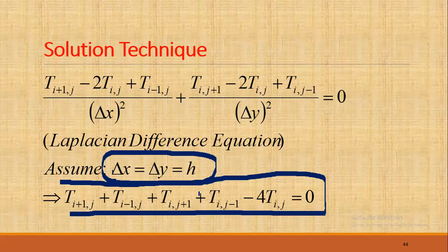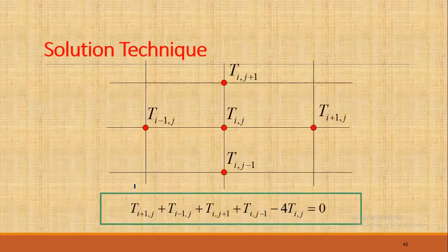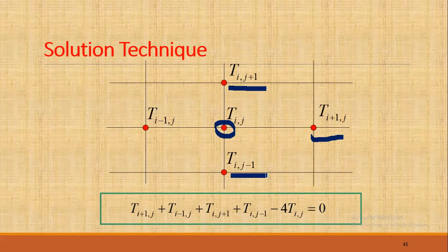And we develop the program in a similar way as we discussed earlier, and we get the solution of the Laplace equation. That means this is T(i,j), this one is T(i,j+1), T(i+1,j), and T(i,j−1), T(i−1,j). So a total of 5 points are included, and we find them and get the answer at each node.